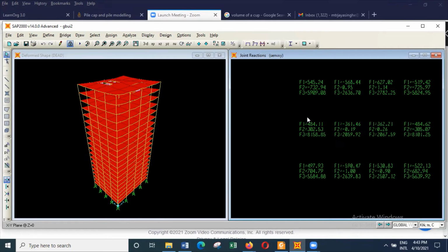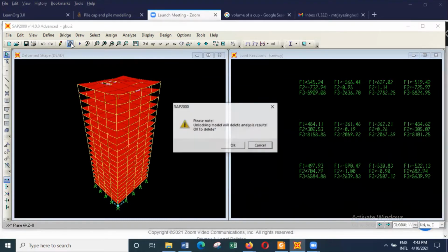which means now we can see, by modeling the pile foundation, what will be the forces that will act on each pile. In this particular case, when I model, it will be a reasonably regular foundation, but you can use the same techniques for irregular foundations as well. So any questions up to this point?